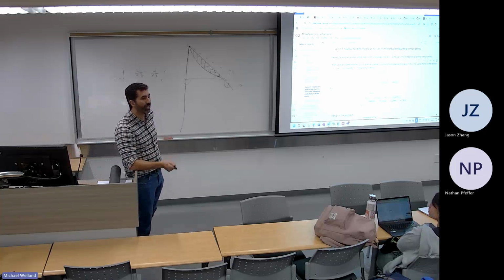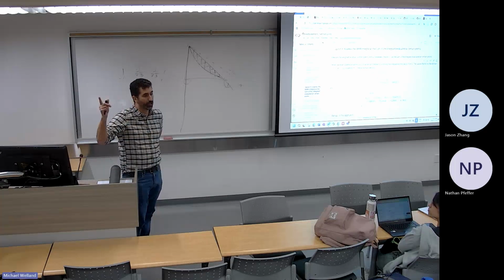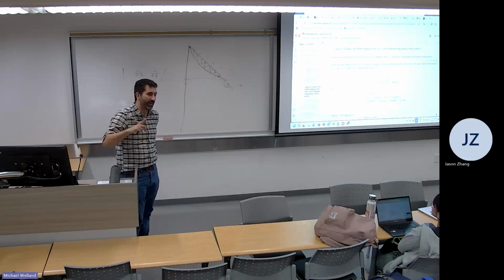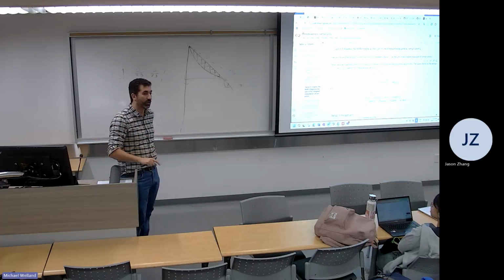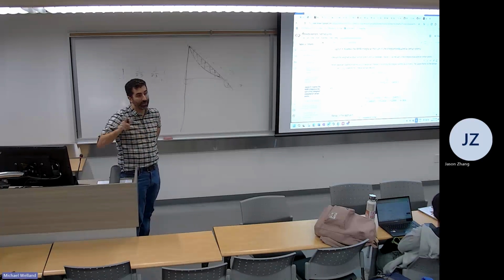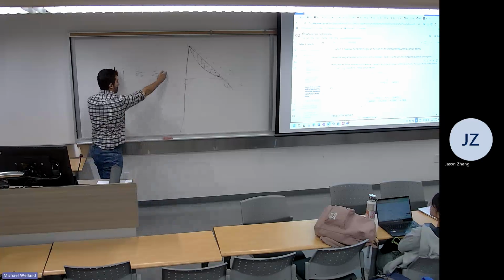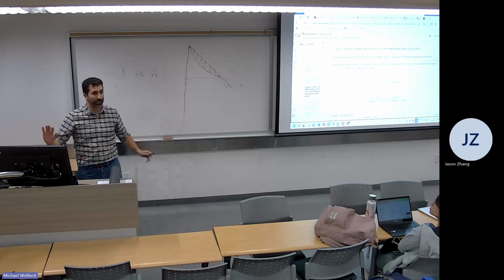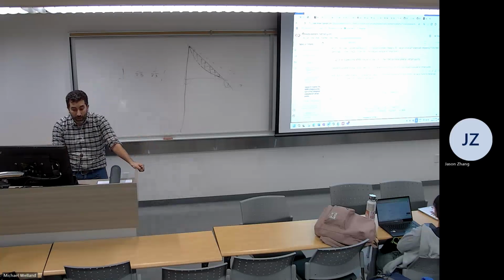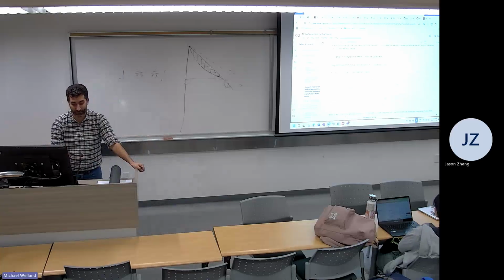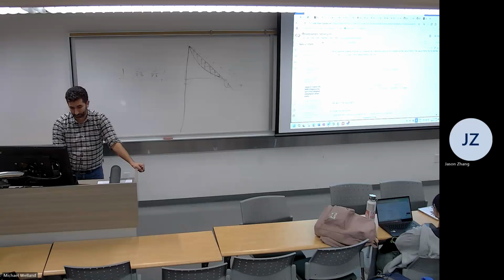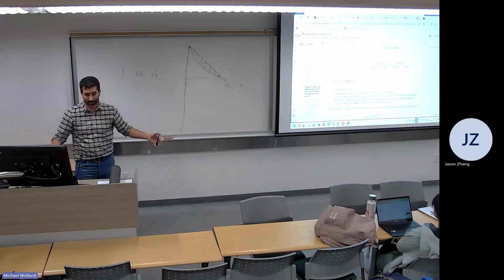The answer is no, it only integrates exactly up to a cubic function, right? Because that's the way that we calculated what the Gauss points were. We had to assume exact integration of a cubic in this interval, and so it only goes up to a cubic. But we can see that this is actually less than a cubic in x. It's quadratic. Okay, great.